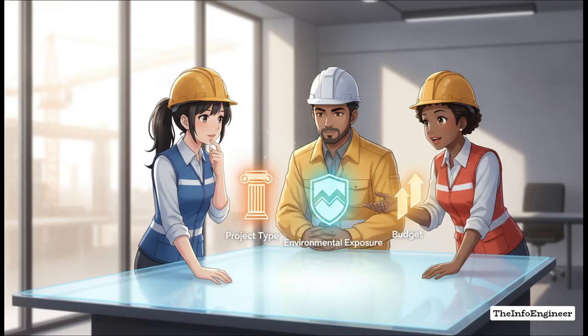Well, here is your practical checklist. First up, look at the project type. Load-bearing structures demand a design mix, period. Second, environmental exposure. If you're dealing with coastal winds or harsh chemicals, you absolutely need a customized, low-permeability design mix. Third is budget. Look, don't be fooled by the lack of initial lab costs for a nominal mix. The long-term material savings of a design mix almost always win out on any larger project.